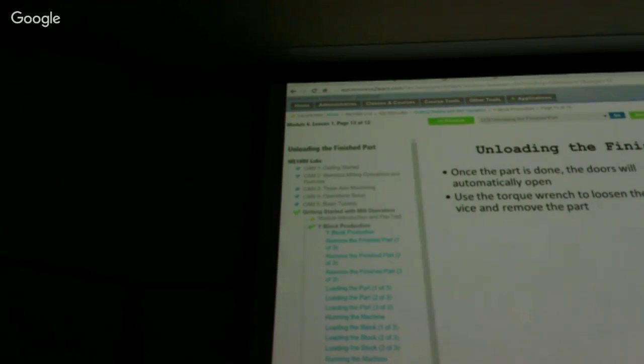So how can I make this shape? Remember I said that the fillets are hard to machine on the outside of parts, expensive to machine? How could I make that shape? I could take a grinder to my end mill. I could make my end mill that shape. It's a little bit more sophisticated than that. You can use the sides of the bit.